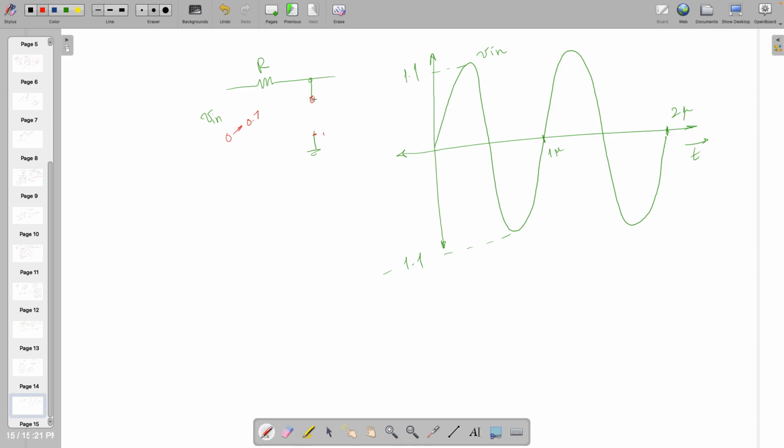During this time when this is off, I am holding a multimeter over here. The multimeter is the one which is going to give me the voltage value, right? So when I am holding it, the input impedance of the multimeter, R mult, is equal to infinity or very high, and this R I kept it 1 kilo. This is around 1 mega, by the way.